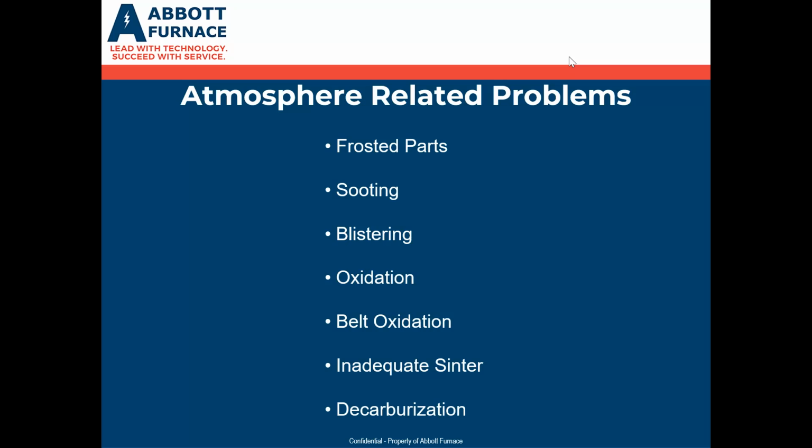A lot of the powder metal guys that are on the line are familiar with blistering. When the lubricant isn't able to work its way out of the part at a lower temperature, and the part gets up to a higher temperature and there's still lubricant available in the part, it boils and blisters the surface of the part, trying to escape.